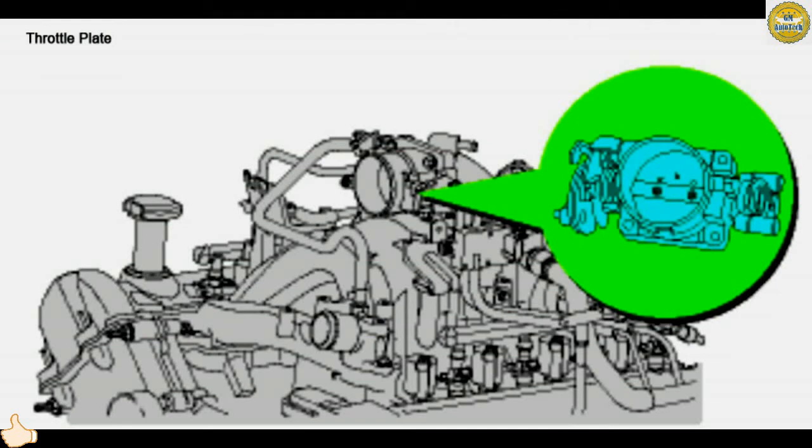A throttle plate is used at the air intake of the engine to control the amount of air allowed to enter the engine. While the engine is idling, the throttle plate is closed. During closed throttle operation, a minimal amount of atmospheric pressure is allowed to enter the engine. Because a low-pressure area is created during each cylinder's intake stroke, a pressure differential occurs within the cylinder between atmospheric pressure and low pressure, which is known as vacuum. Vacuum is high, 58 to 75 kPa or 17 to 22 inches Hg at idle with the throttle closed.